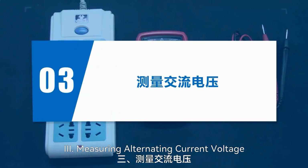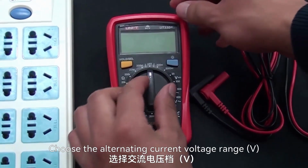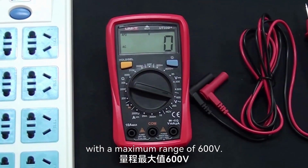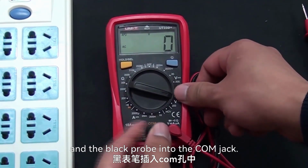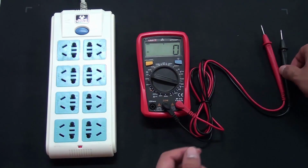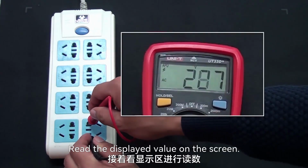Three, measuring alternating current voltage. Choose the alternating current voltage range with a maximum range of 600 volts. Insert the red probe into the volt-ohm milliampere jack and the black probe into the COM jack. Place the red and black probes into the two holes of the socket. Read the displayed value on the screen.